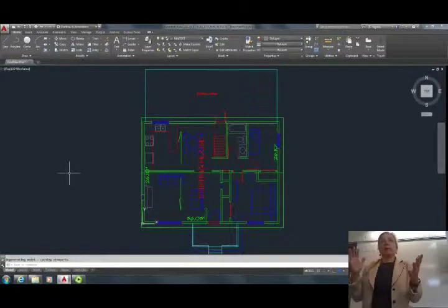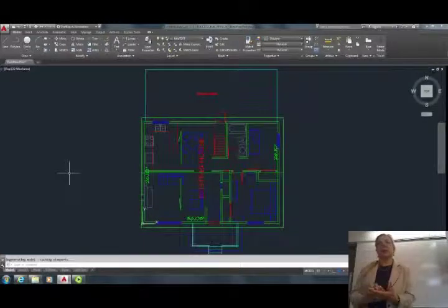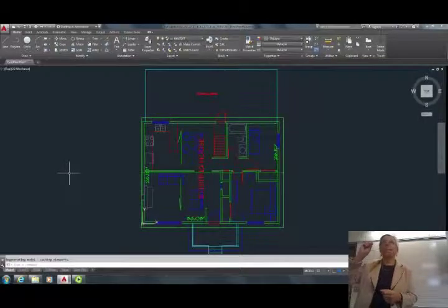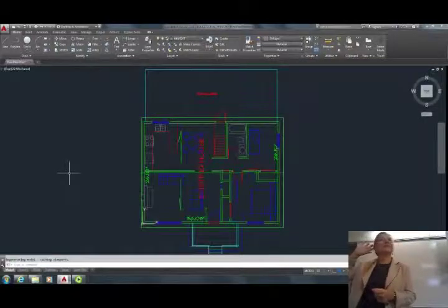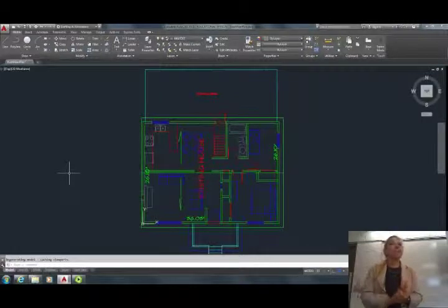Our sheets that we are working on as the basic standard sheet is the small sheets, 8.5 by 11. Do you remember from drafting what is the standard size of text for construction drawings? Architectural, civil, transportation. Do you remember the standard height? Louder. 1/8 of an inch, or 3 millimeters, okay?